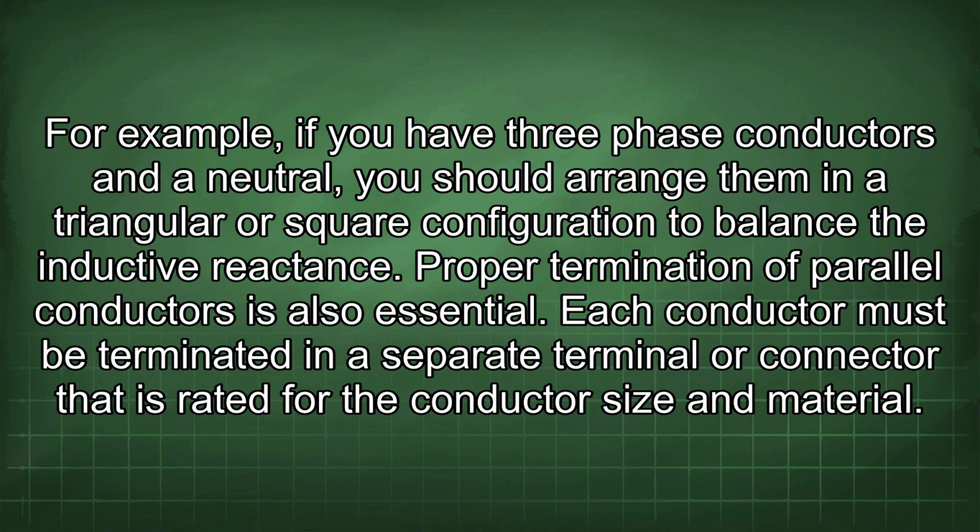Proper termination of parallel conductors is also essential. Each conductor must be terminated in a separate terminal or connector that is rated for the conductor size and material.